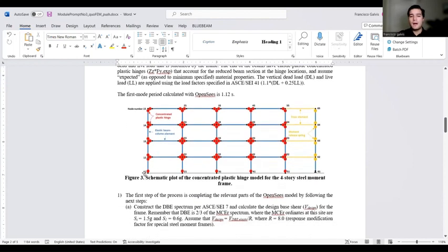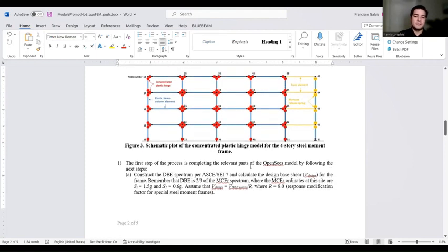Where you have all the nodes numbered here in black, and those are the nodes that control each of those grid corners where the beams join the connections. We also have a truss element here that connects to a leaning column that provides the effects of the mass of the gravity system corresponding to this frame that's responsible for taking the lateral forces.